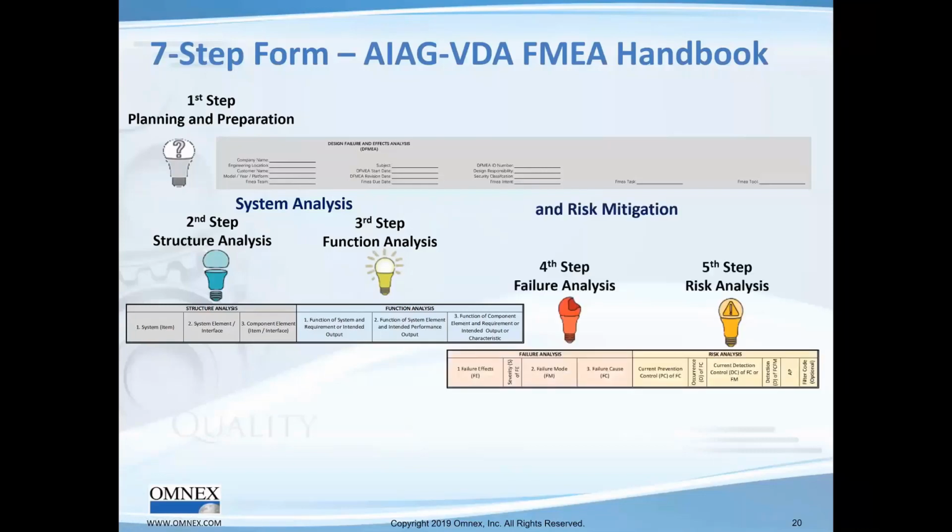Next, at this point, the 3 different levels do continue into the 4th step, where you're looking at the failure mode, and it's a very key step, folks. Once you have the functions and requirements, typically Germans stop at the function level. If you look at the VDA FMEA, they stop at functions. Really, of course, the 4th edition always looked at functions and requirements, and that's what we would recommend. Look at functions and requirements, and look at the failure mode.